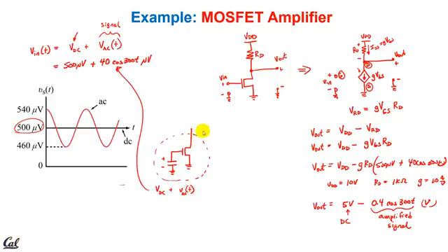And so what happened when we connected our electret, what did we do? Remember, we had a VDD up here and we had a resistor, and then this was our output. Oh. That's what was going on. It was a single transistor amplifier. So we had a large DC voltage, and then we had a little signal there. And why did we put the cap here? Remember? We didn't want the DC voltage to move on to the next part of our circuit. We had to filter it out. Yeah, get rid of this. That's right. That cap got rid of that part.